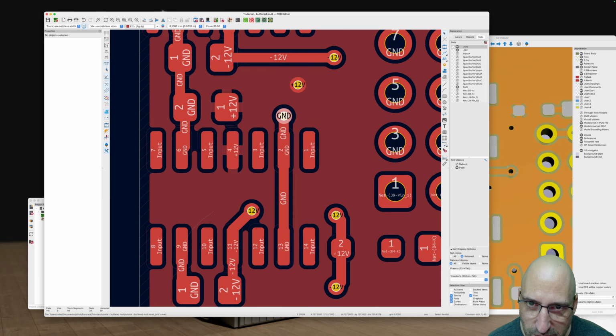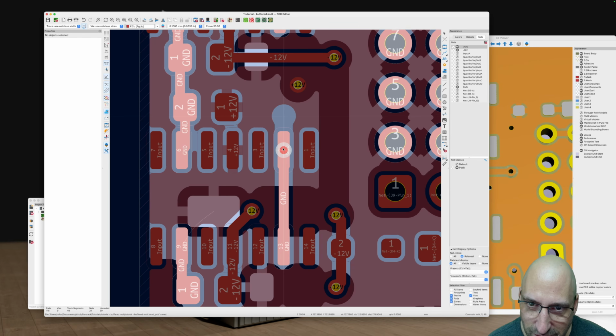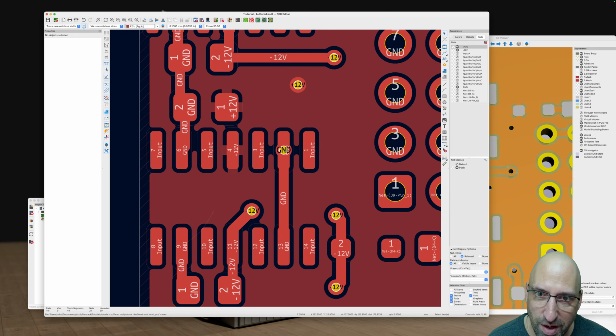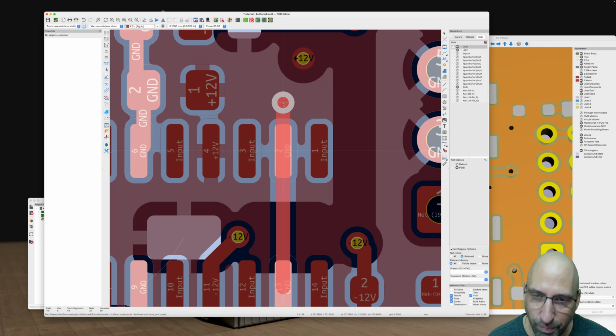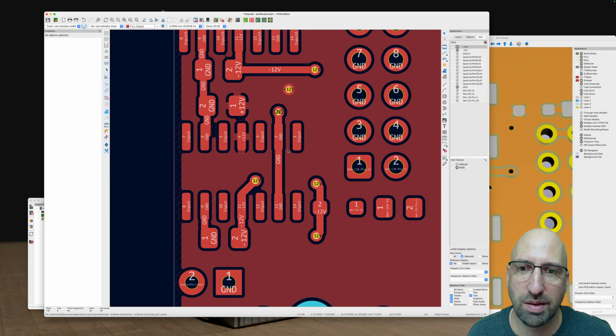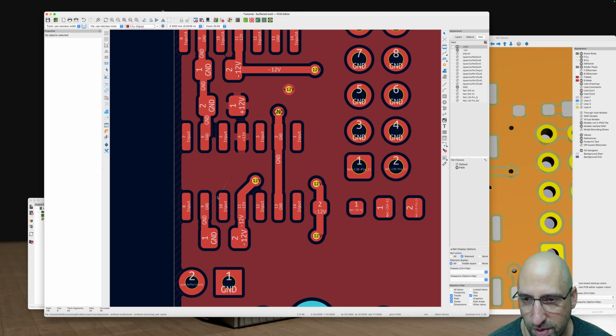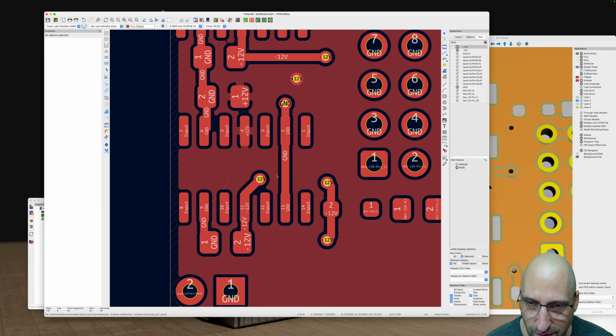You might also be tempted to, and I used to on my old designs, just drop the via straight on the pad. Wherever you can, avoid doing that. It's not good practice. I don't know all the reasons. I guess it's just to get more contact for the chip that's going there.